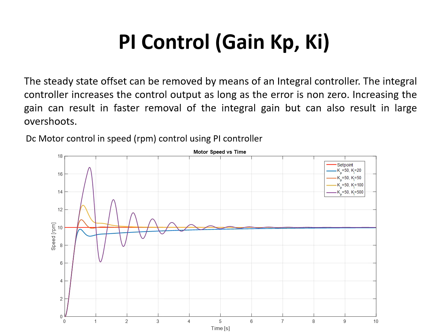So with the previous slide, we saw that as we increase the gain Kp, we basically reduce the error, but we could never have a 0 error term until Kp effectively approaches infinity. So in this case, by simply adding an integral term, we can see that the error approaches 0 irrespective of the Kp value. Right, so you can have a very low Kp value, the error will eventually go down to 0. It just might take a long amount of time.